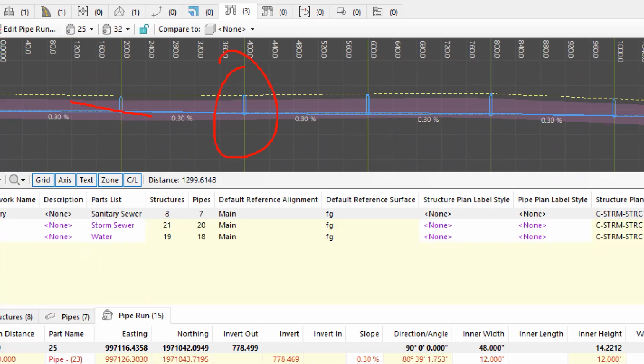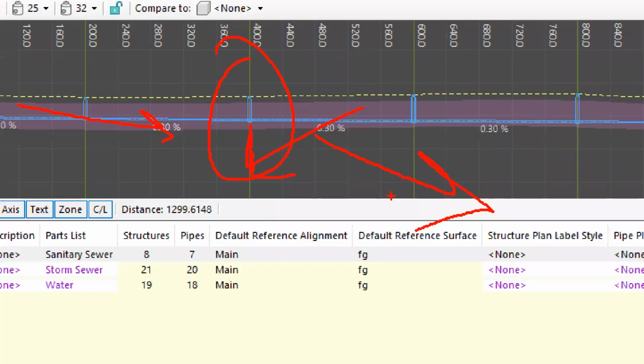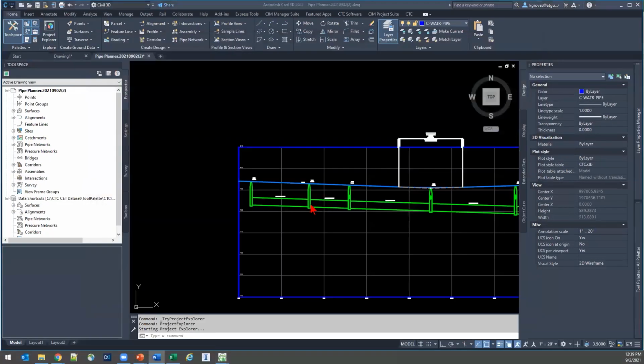Well, we got to go shallow into it, and then we got to go steep out or something else. Or maybe, hey, you know what, this is actually going to be a low point, and we got to go down into it. So if I've got that whole pipe run, I can't apply a uniform slope and get the values that I'm looking for.